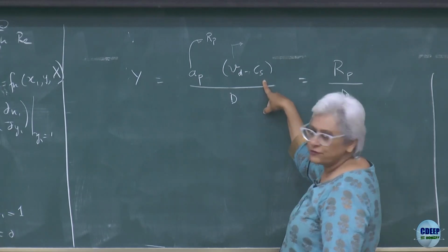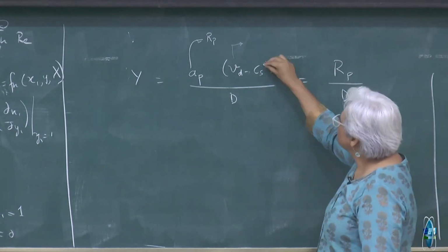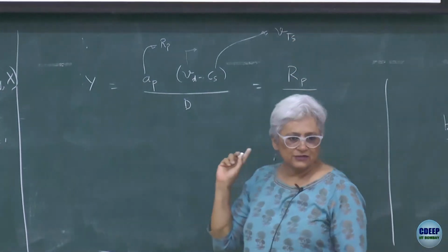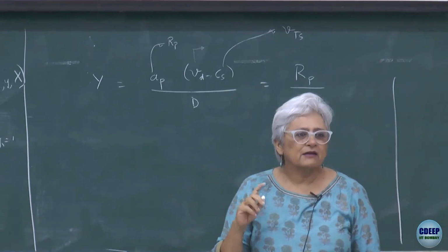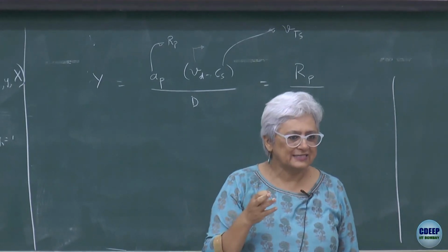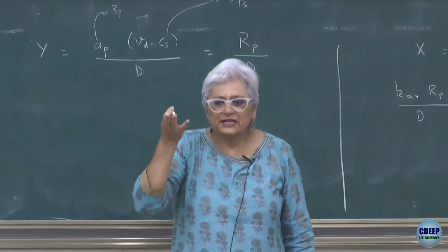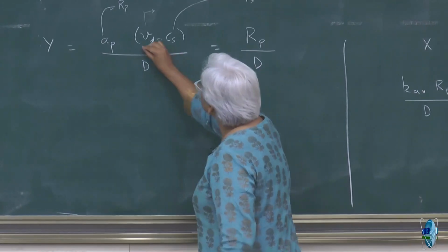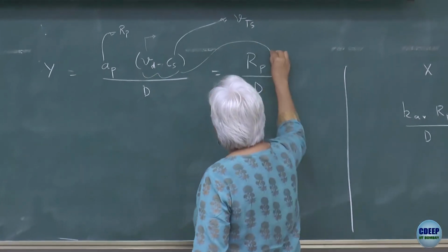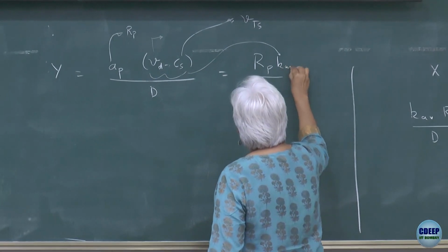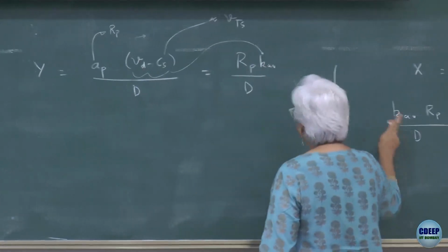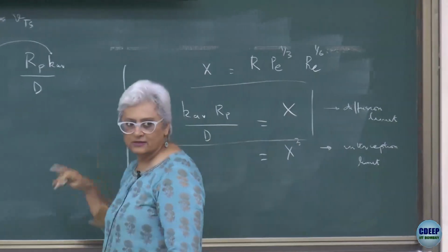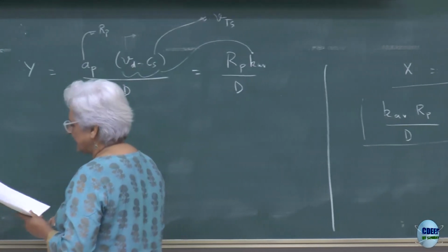Now, this deposition velocity, we said it's equivalent to a Kavg. What are they removing from it? They are removing a terminal settling velocity from it, just to make sure that they're keeping the interception idea and removing any gravitational settling, right. So, this whole thing over here is nothing but a Kavg. And that's what you have on this side of your equation, right. So, that's what they've plotted on the y-axis.